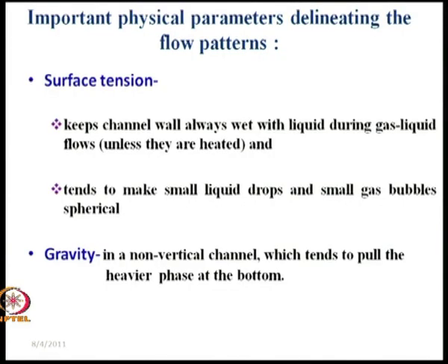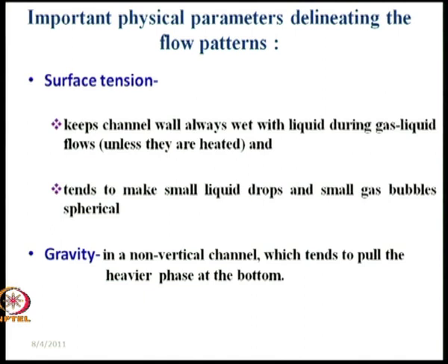Well, the other very important thing is gravity. Okay. Gravity in a non-vertical channel, naturally what does it tend to do? It naturally tends to pull the lighter phase to the top. So, we will always have some sort of stratification where the lighter liquid or the lighter gas, whatever is the lighter phase, will be on the top and the heavier phase will be on the bottom. So, due to these two factors, more or less some order can be brought about in the apparently chaotic study of flow patterns which we feel.